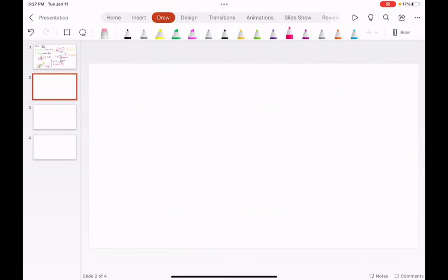Where did those come from? Those are theories, right? What are theories? You observe something experimentally and try to come up with a scientific explanation, like, hey, this might have happened because of that, and that is why we are seeing this. Those theories came because of the experiments. So for example, if you have an aluminum rod or an aluminum dog bone specimen, you put that in the tensile testing machine and you break it slowly, you would observe, interestingly, that all aluminums fail at 45 degrees. Why?